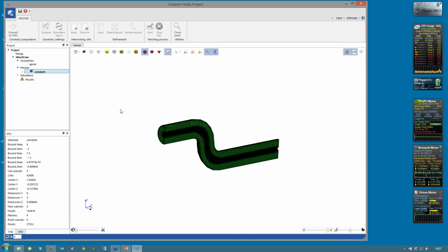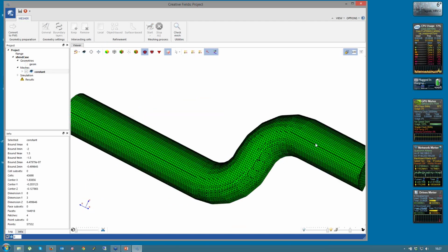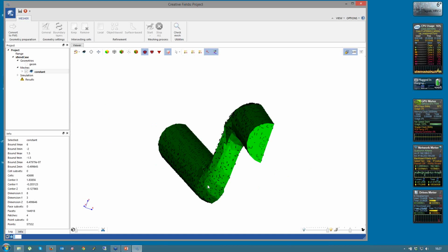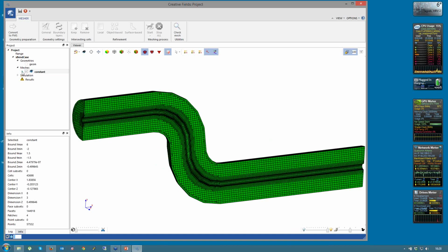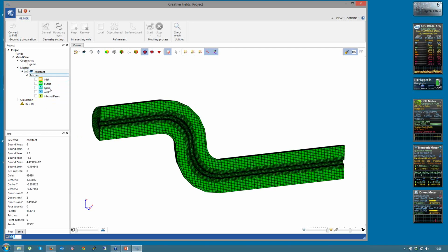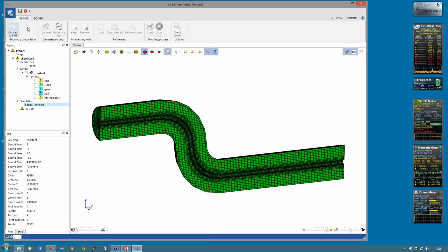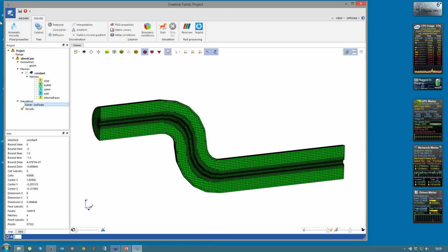Now when we load the mesh, we see that we have a coarser refinement here, and a very fine refinement here on our facet subset. When we check here, we see that the patches are transferred to the volume mesh, but no facet subsets. Now again, we are ready to prepare for our simulation. We will select the icoFOAM solver, and now we have the solver ribbon ready.